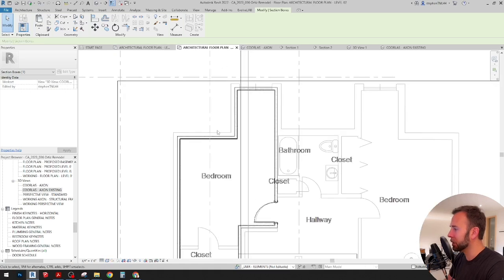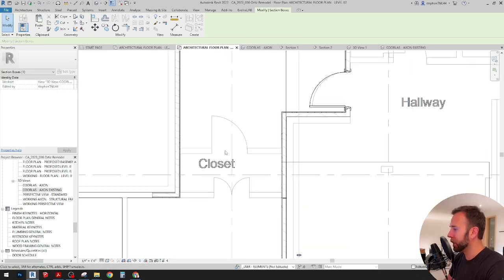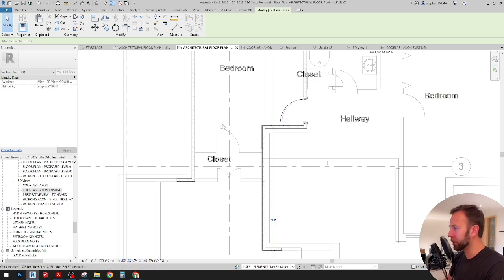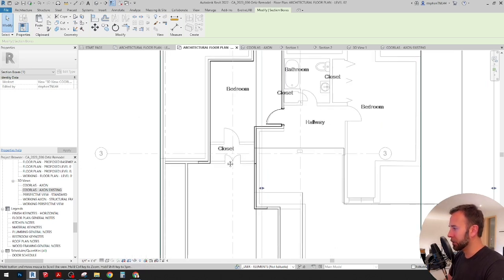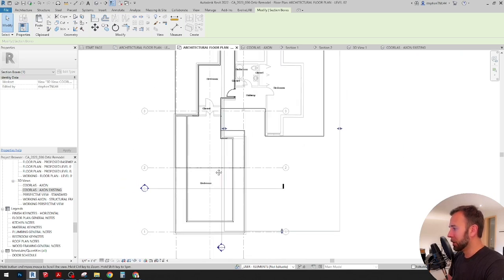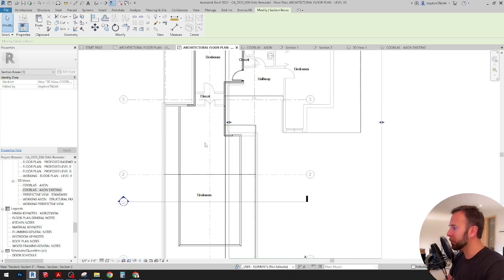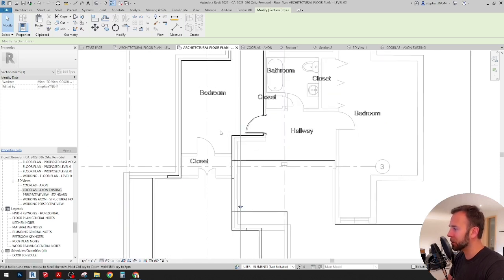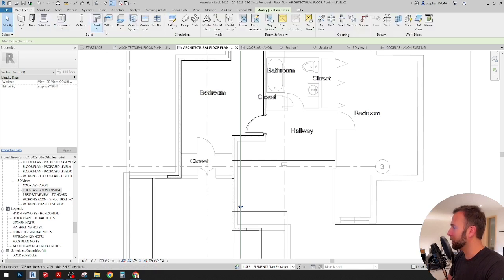So let's do that. Let's drop our ceiling plane in. Now these two existing walls I have kind of ghosted in from the survey drawing are going to be demolished to open up the existing bedroom space into this attic space. So like we said at the beginning, pretty unique configuration of the bedroom area. Very long, narrow space, but wanted to be used as just additional lounge space in the bedroom. So that's been cut out, but I do have the soffit above going up to the underside of the ceiling here. So I can draw in my ceiling,